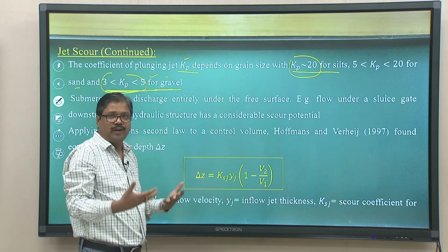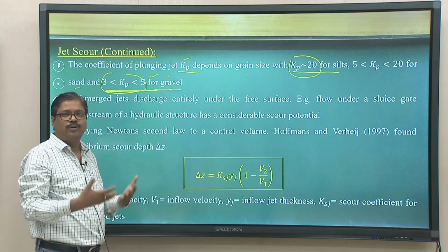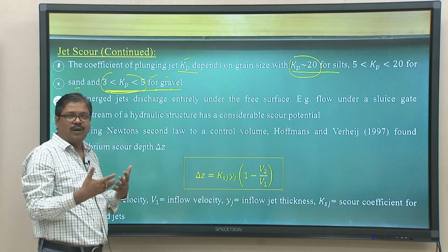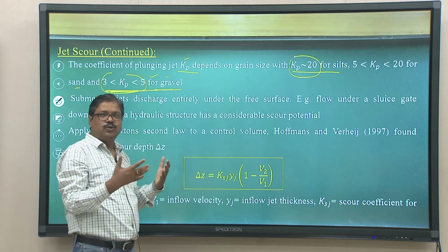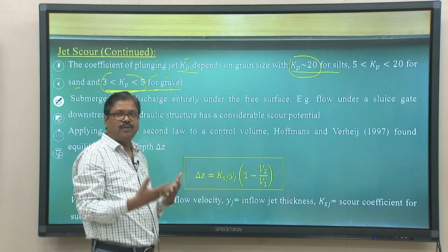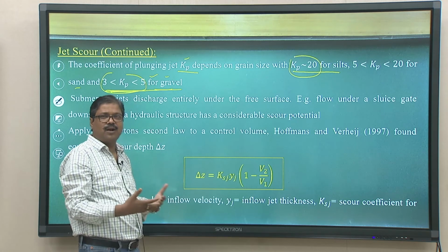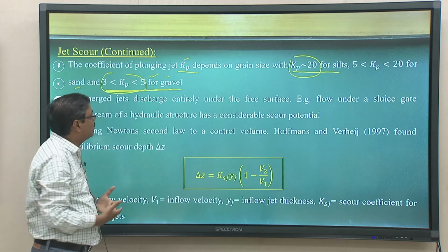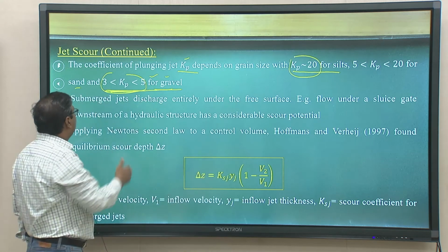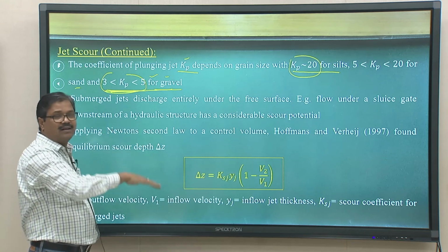So, we do not know what type of flood is going to come, and in that period how do we manage it? What could be our strategy to look at the safety of the dam and the weir structures, because we have to protect against the scouring mechanisms, protect the scour holes. To protect the scour holes, we should have this knowledge of scouring, and how we can manage it with the gravels or tailwater depth.